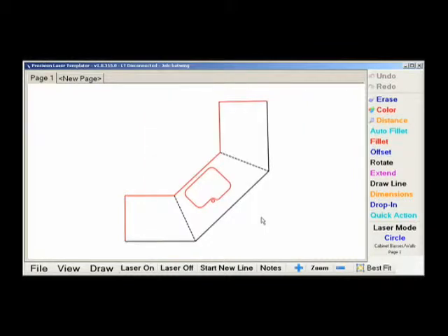Before we start learning about the software, we need to understand a basic function about the template, and that is snap points. All lines have snap points, and what they are simply locations of significance. Snap points are located at the ends and midpoints of all lines. Also, whenever 2 lines of any kind intersect each other, they create a new snap point. Snap points are a great way to insert sinks and drop-ins, which we'll discuss in the drop-in section.